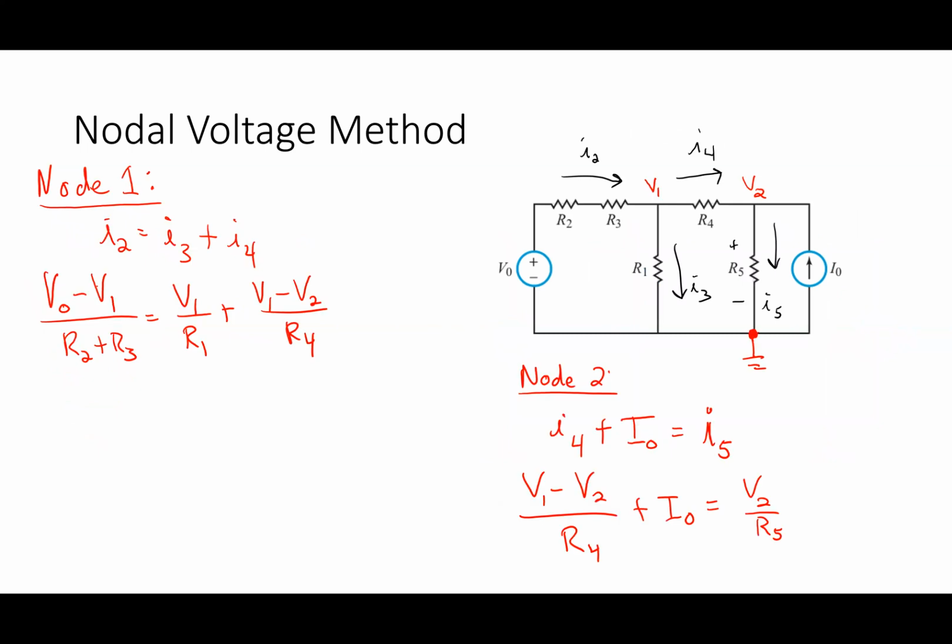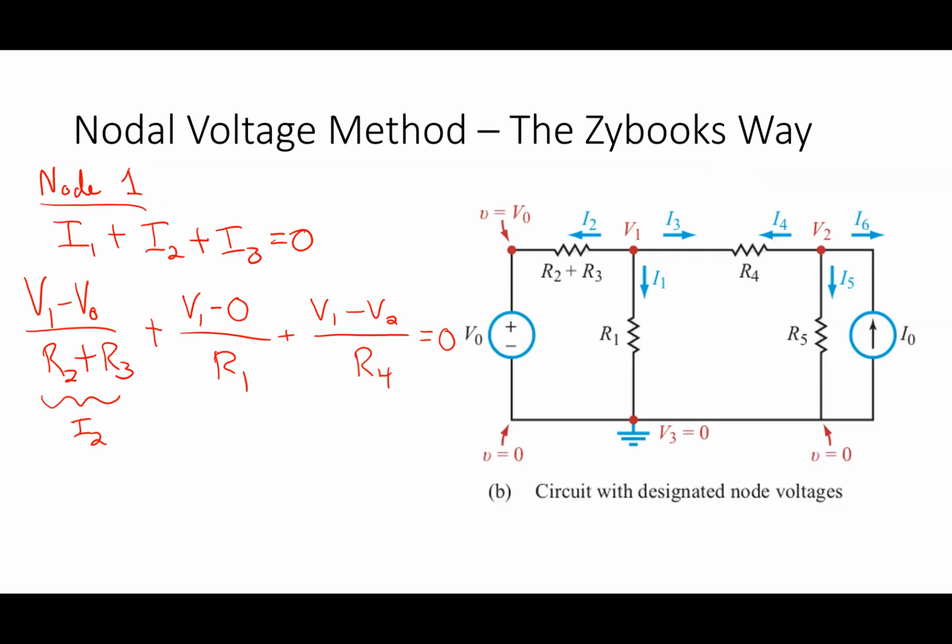If you compare that to the equation I got doing it the other way, which is a lot more traditional to write, because it just requires me to know Ohm's law and KCL, right? This way uses a trick. The node you're leaving to the node you're going to is a trick that's kind of simplifying the passive sign convention a little bit, okay? Nothing wrong with it per se.